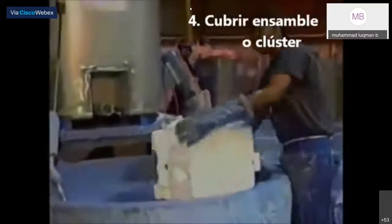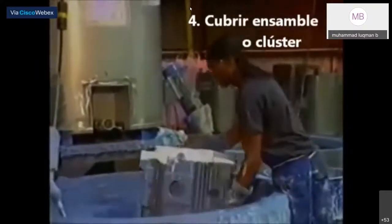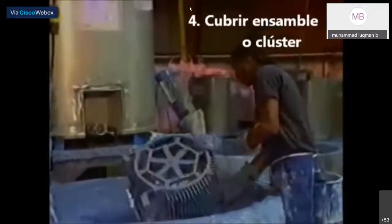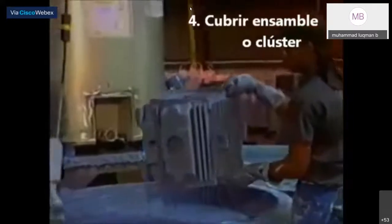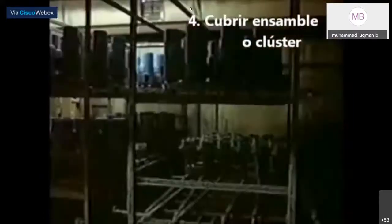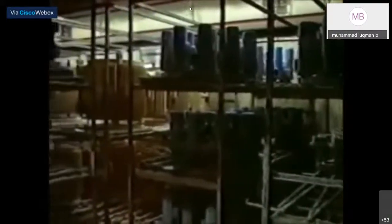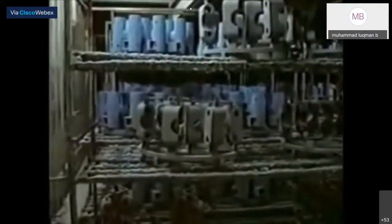Foams or clusters are then dipped in a water-based refractory coating which covers all surfaces of the foam, including internal passages. The coating will now have an internal surface equal to the outside surface of the foam. The wet, coated foam cluster is then placed in a drying oven to remove the water. Ideal process control and throughput are achieved with dehumidification and internal humidity control.